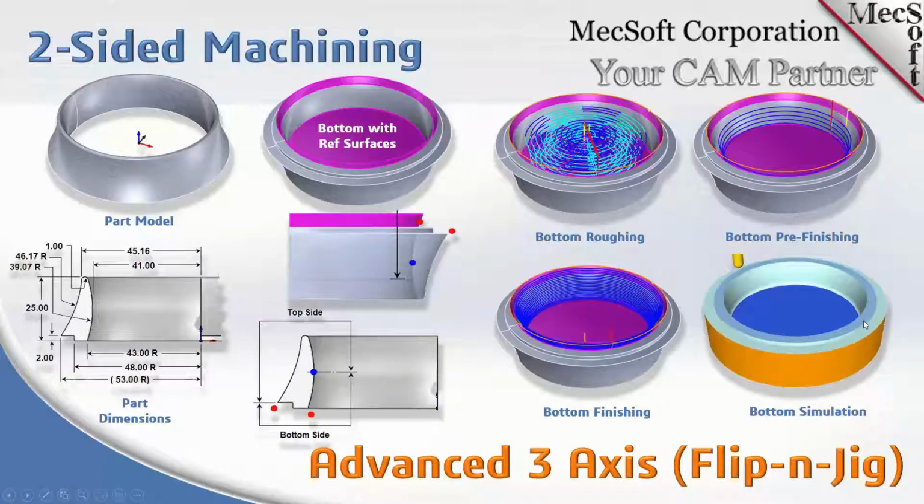This is what it's going to look like after the bottom side is machined and you take it off the bed. So you're still going to have a circular stock. You're going to have your flange machined, and then you're going to have half of the inner area machined down past the quadrant plane. And this is the surface that we modeled so that the tool wouldn't go past. So now, depending on the operations you use, you can contain your tool path in the Z-axis. In this particular case, it was more convenient to just put that surface in there.